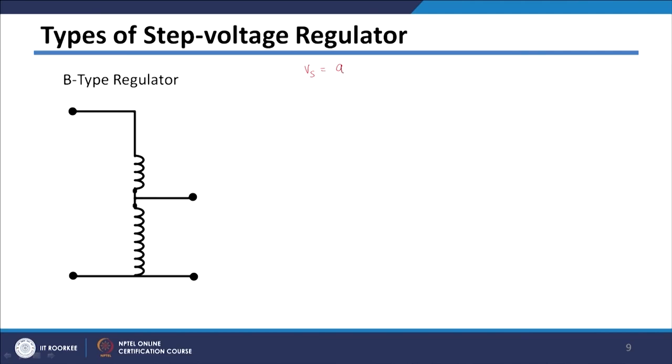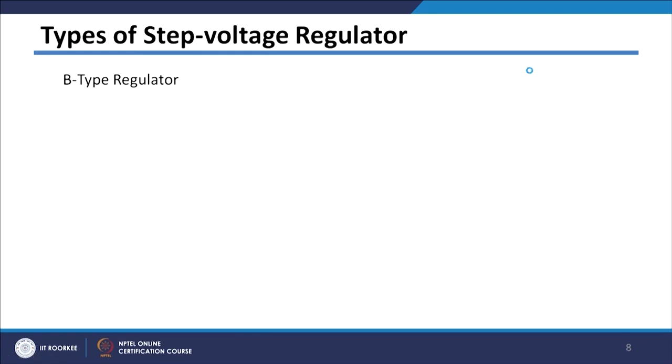So, basically in this connection we have got two equations, which is basically Vs will be equal to AR into VL is one equation, and another equation which is Is, which is equal to IL divided by AR, which is second equation, and this AR will be equal to 1 minus plus N2 by N1, because when it is raise we are getting minus sign, as we have discussed in slide.